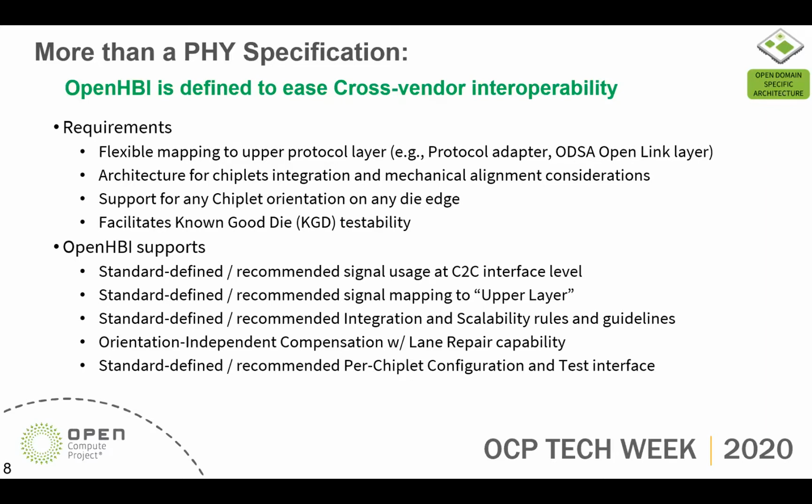It must support any chiplet orientation on any die edge of the anchor or the SoC, meaning that if you put the chiplet on a different side, they will continue to work and continue to be routable. And to the extent possible, the spec should facilitate non-good die testability.